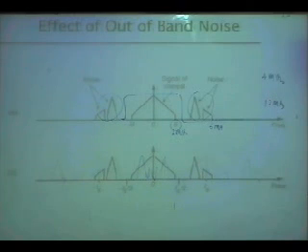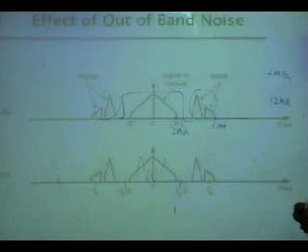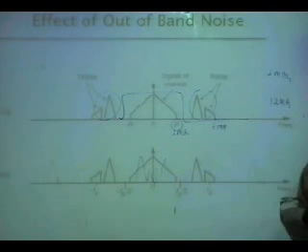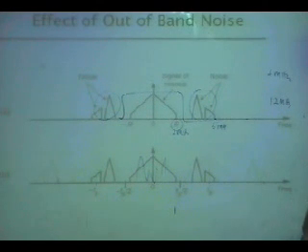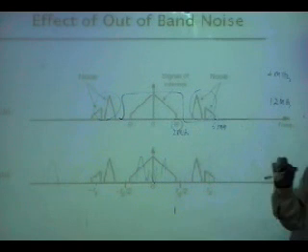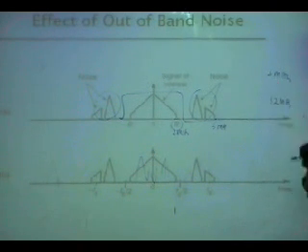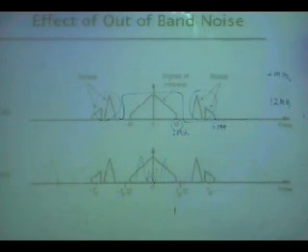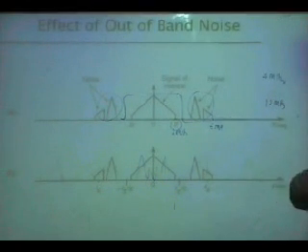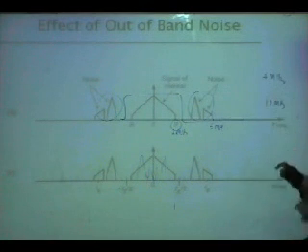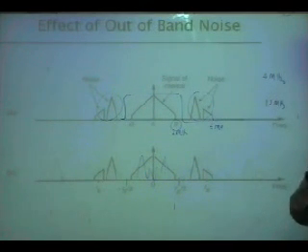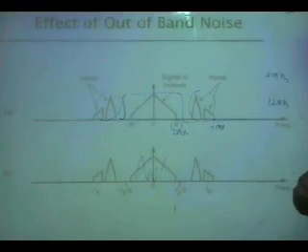Then you throw away samples. You say, I need not have 12 million samples every second now, because I know I don't have the outer band. I have cleaned the noise digitally. So from here you go to here. You throw away every 2 samples, or every 3 samples. So keep 1, throw 3, keep 1, throw 3. If you do that, you again get to 4 megahertz. So you never keep more than what is required in communication, in video, image, or whatever processing you are doing.